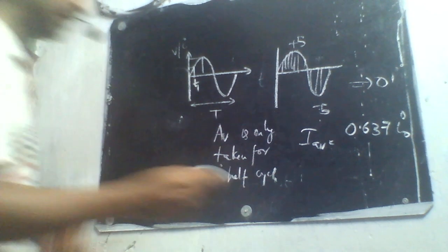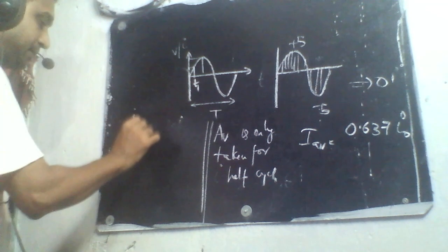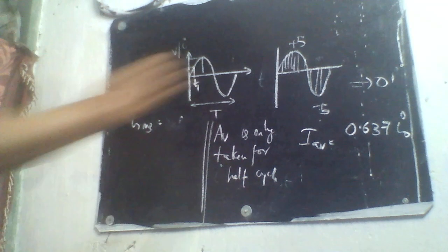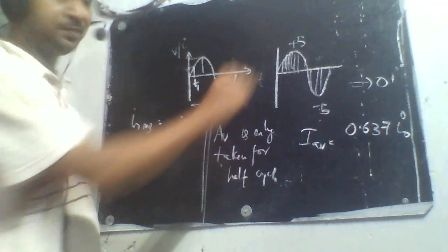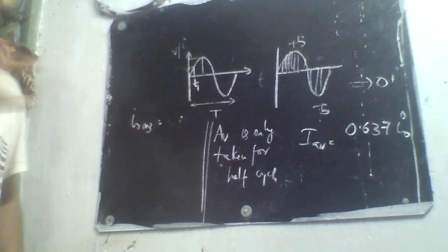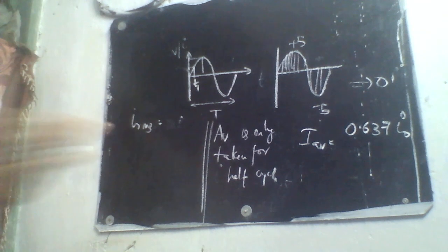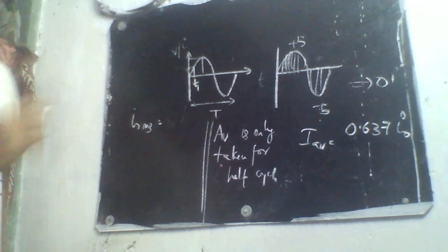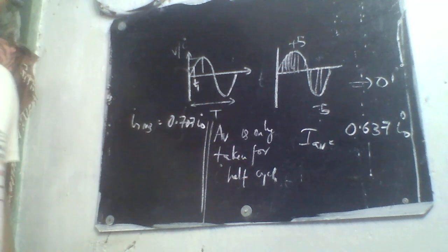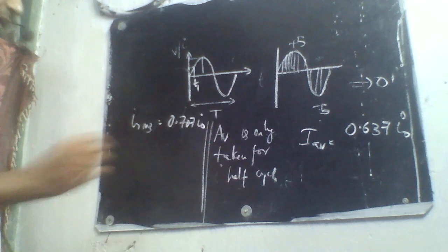Note down this equation. Similarly, another term to be used is RMS value. I RMS, RMS means root mean square value. They will divide this into small intervals, find I for each, then square it, then take the average, then take the root. That is how the root mean square value comes in. You need not look into it, you only need the equation. I RMS is equal to 0.707 times I0.